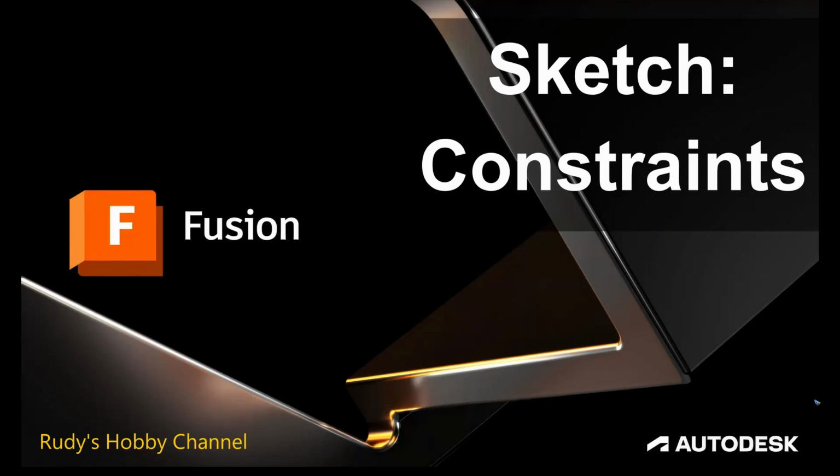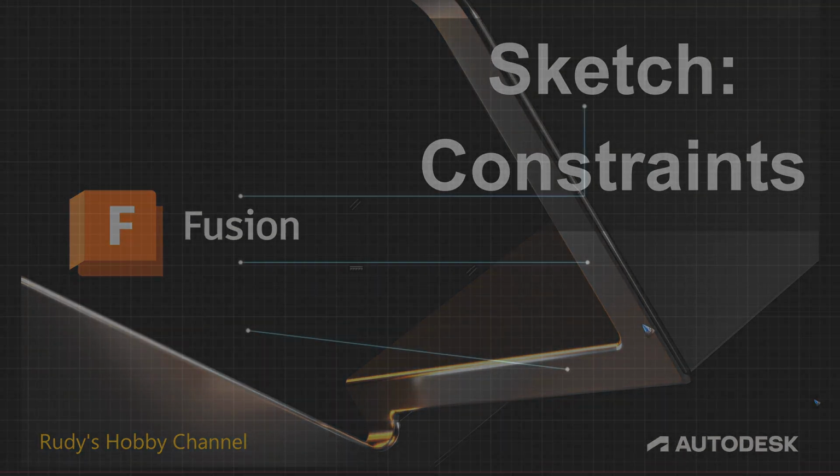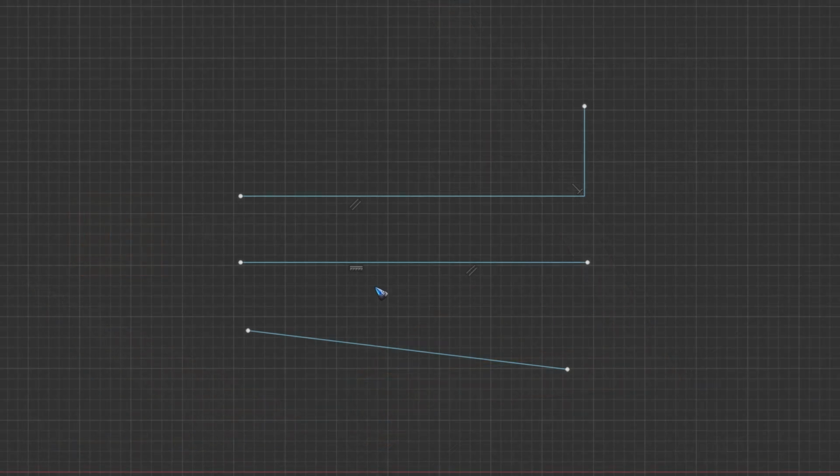Welcome to this video where we have a look how we can constrain geometry in 2D sketch mode of Autodesk Fusion. In the previous video we saw these icons pop up. This is a horizontal icon, this is a parallel icon, and this is a perpendicular icon, and they were the result of inference snapping. This line does not have any icons, which means I can pick up this point and this line is totally free to move around.